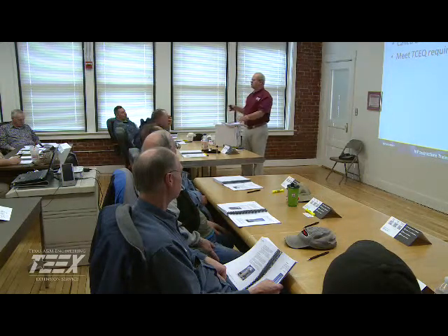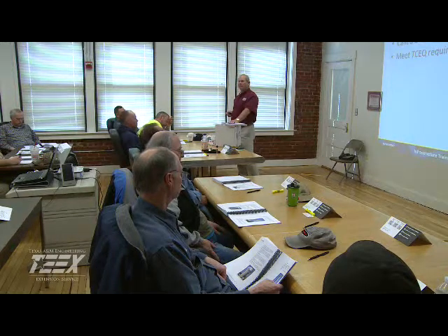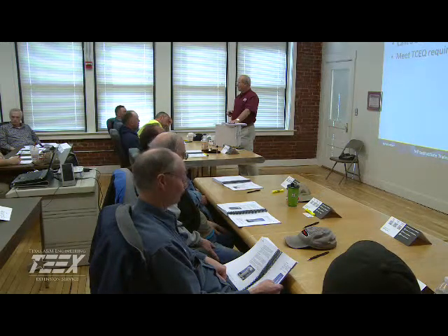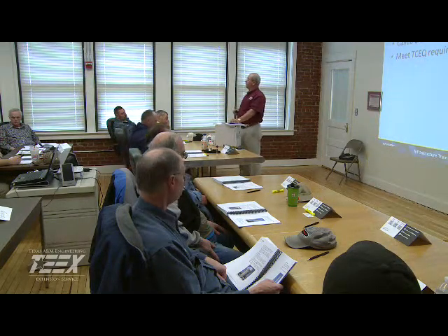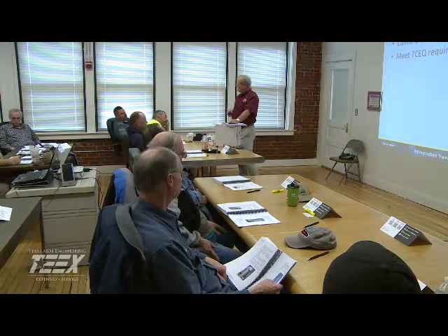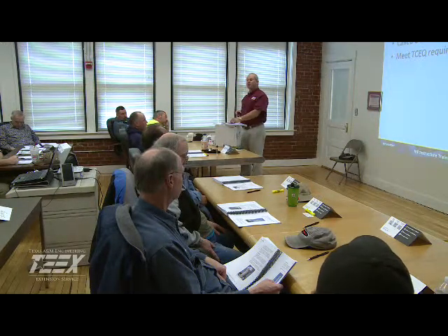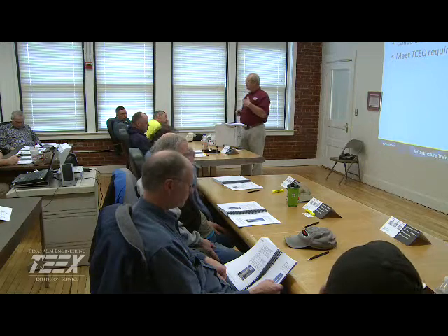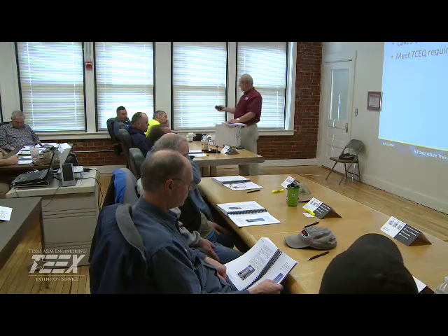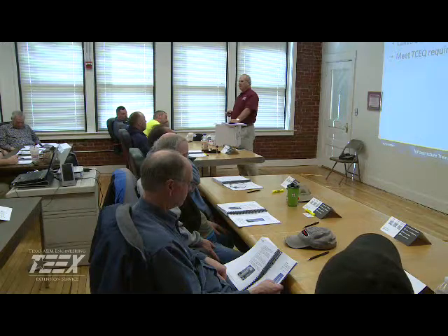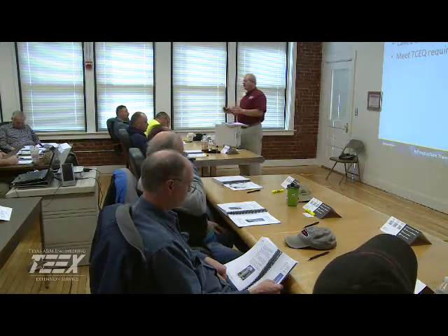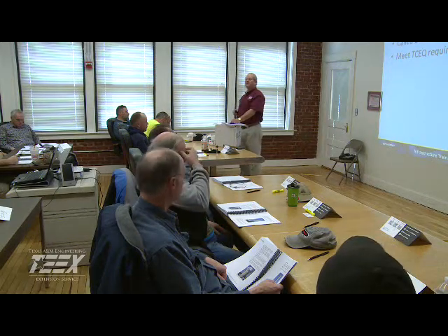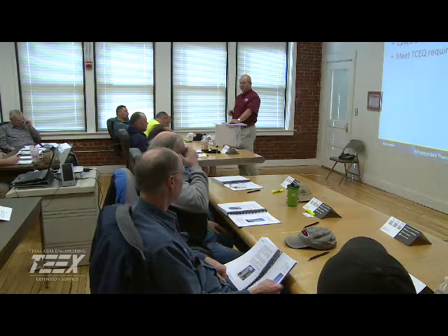Do y'all know what your capacities are here in Rhode Island? Any idea? Now, in Texas also, they allow you to use pressure tanks. The EPA allows you to use pressure tanks for small systems and even in large systems. In Texas, just as an example, and you can find out what your state requirements are, if it's pressure tanks, the largest tank that we can use is 30,000 gallons, and it's good for 2,500 connections.